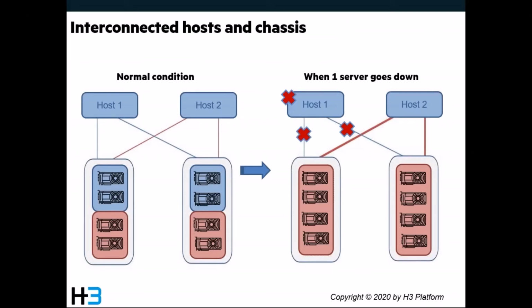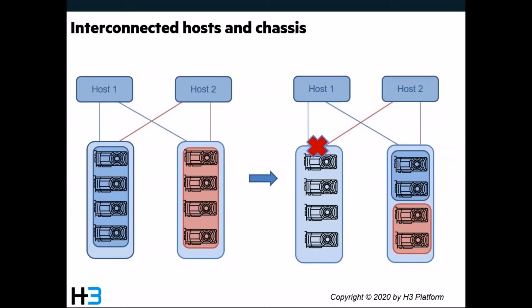So we can construct a system similar to a high availability infrastructure using multiple Falcon 4010. Imagine you have 2 hosts. Each of them takes 4 GPUs now. And when one of them does not require so many GPUs anymore, the other host can take over the GPUs directly. The other way around, when one chassis is out of order, your host can share the GPUs in another chassis.